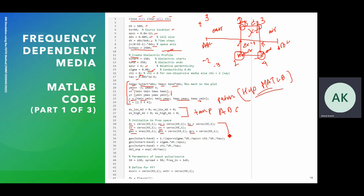Once we have initialized all the variables, then we initialize them for the dielectric space. For example, this particular region was air. So this was already initialized as gx was 1, gbx was 0, and gcx. If the entire region was just air, this would have been fine. But since over here there's a region where we have a dielectric material, this region will have different properties.